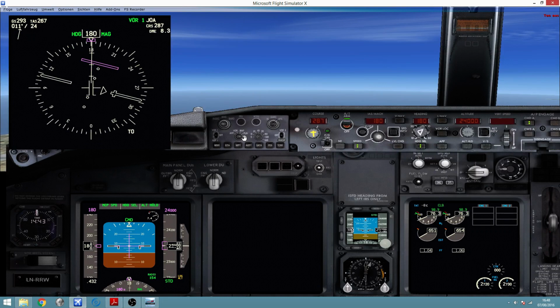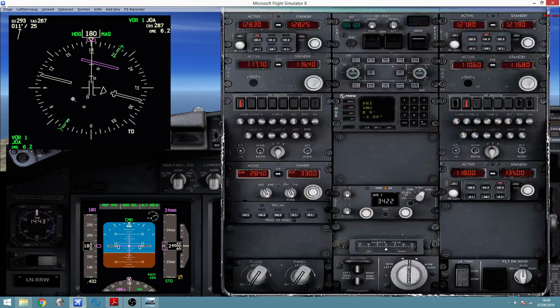All right, so for the exercise that we'll perform in this practice, just be aware that you can either select VOR or APP, which stands for ILS. And since we are going to use VOR, here we have the DME readings. Be aware that we have a couple of needles that I want you to move up. So go here to where it says VOR 1 ADF 1 and click on the right button of the mouse, and then you will here be reading the DME, the distance to the station that you've monitored on VOR number